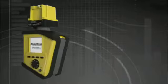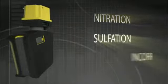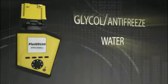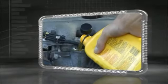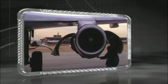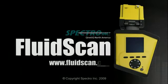The FluidScan provides immediate on-site analysis of lubricant properties and accurately warns the user when it's time to change the lubricant. It measures total acid number, total base number, oxidation, nitration, sulfation, incorrect lubricant, additive depletion, soot, glycol antifreeze, and water. FluidScan's primary benefits include extended oil change intervals, no delay in waiting for laboratory analysis, reduced operational and maintenance costs, reduction of unscheduled maintenance outages, and prevention of catastrophic failures. The FluidScan is the ideal on-site oil analysis tool for your condition monitoring needs.